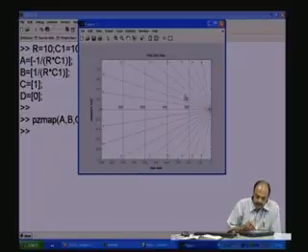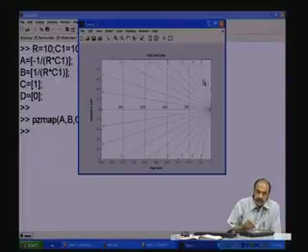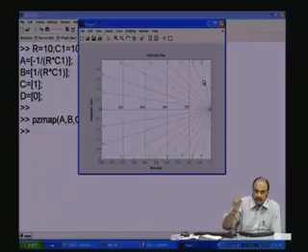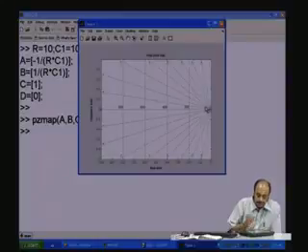As you start going towards the imaginary axis or the omega axis, you will have larger amounts of oscillations, but which will gradually decay at a rate depending upon the projection value on the x axis.